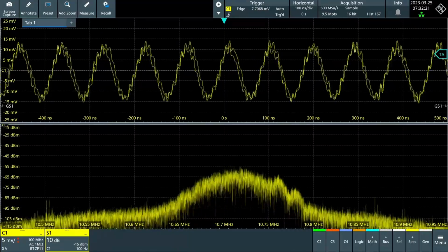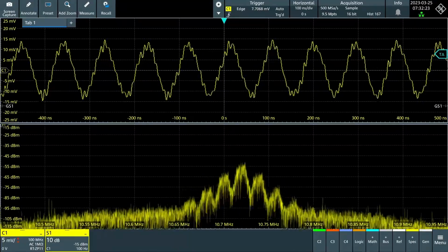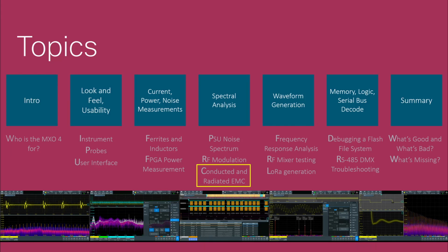Another neat use case for the spectrum analyzer functionality is to perform EMC testing to see what unwanted content is emanating from the equipment under test. The type of testing I'm thinking of is that which could be performed more frequently than pre-compliance tests, and of course at a far lower cost than formal testing in a lab. In other words, I was curious if EMC testing on the fly could be performed during product development.